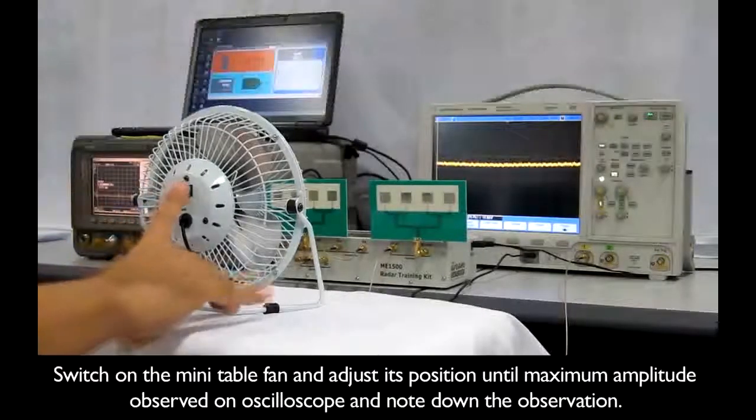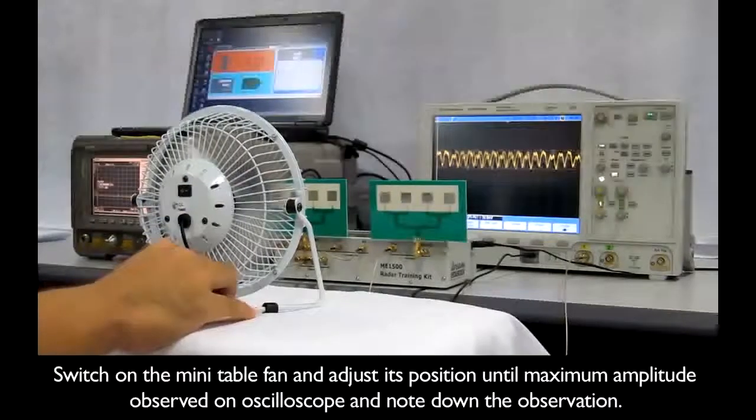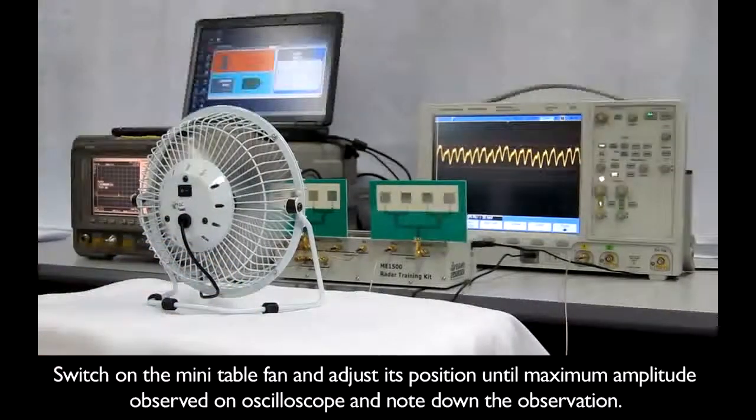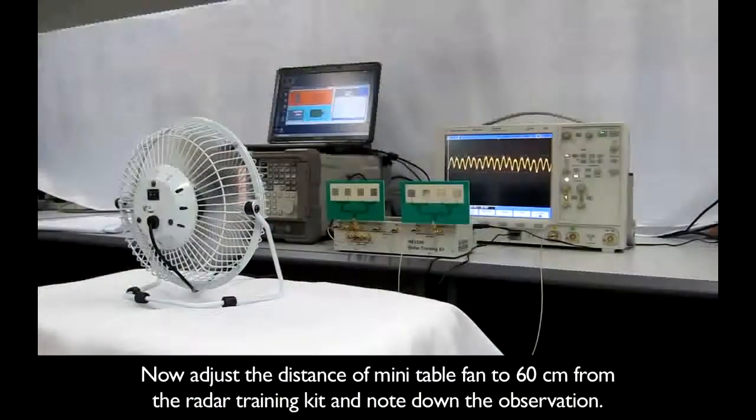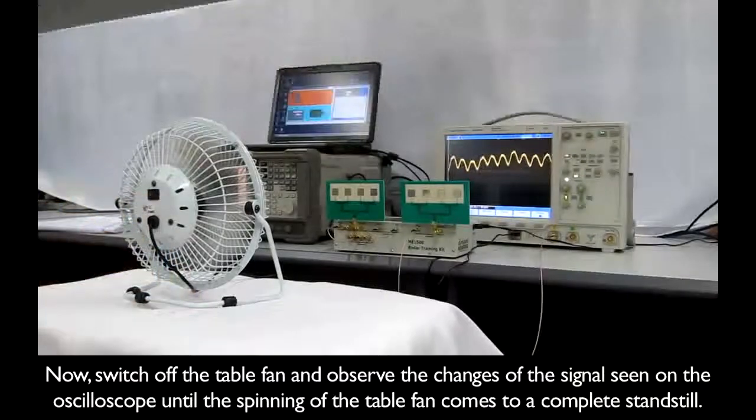Switch on the mini table fan and adjust its position until maximum amplitude is observed on the oscilloscope and note down the observation. Now, adjust the distance of the mini table fan to 60 cm from the radar training kit and note down the observation. Now, switch off the table fan and observe the changes of the signal seen on the oscilloscope until the spinning of the table fan comes to a complete standstill.